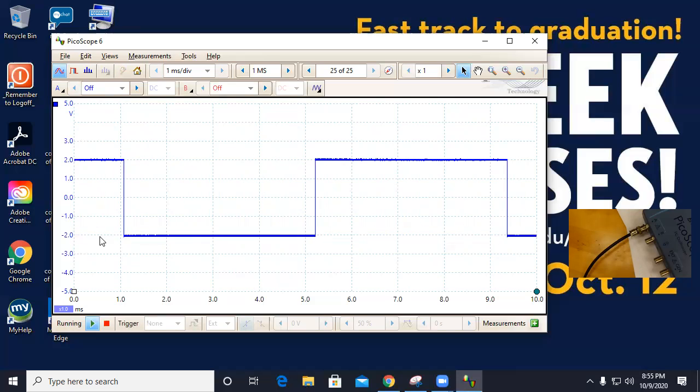All right, I got from -2 to +2. How did I do that? I changed the knob of the amplitude in the function generator, and I can also change the frequency of the same thing. So this is the way you can see everything on the screen.